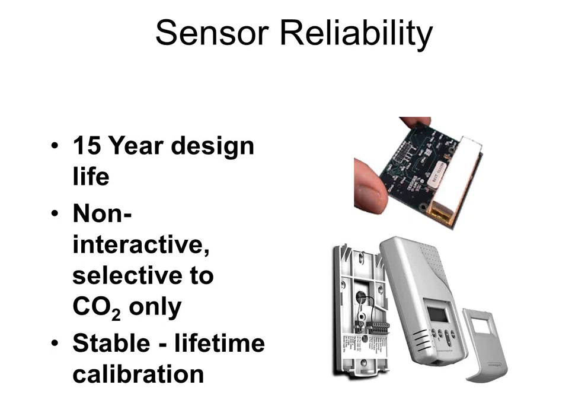All of the commercial grade CO2 sensors have gotten rid of the calibration option. You cannot calibrate them anymore. You can get industrial ones, and those can be calibrated and should be. But for the commercial use ones, offices and schools and all of that, there's no calibration allowed on them anymore. They took the button off because people were pressing it at the wrong time. Instead, they give you a 15-year design life for this sensor, so it should not go out of calibration. And most of them give you a 10-year guarantee on the calibration.